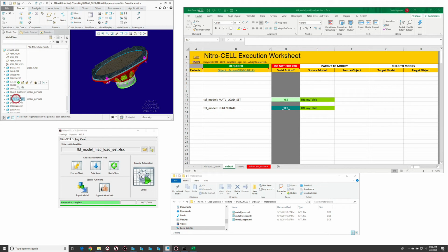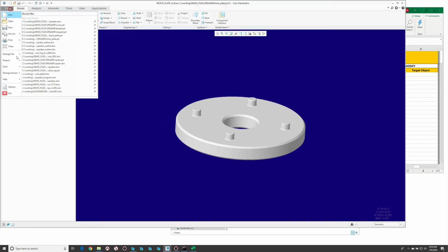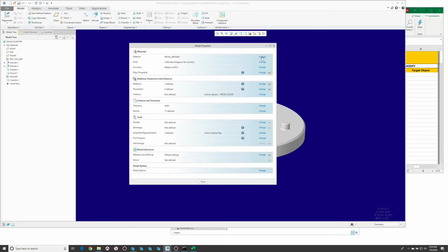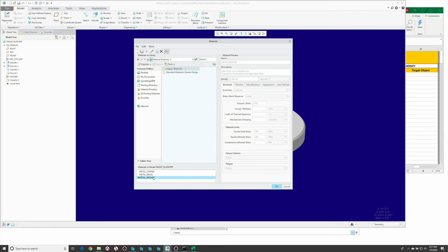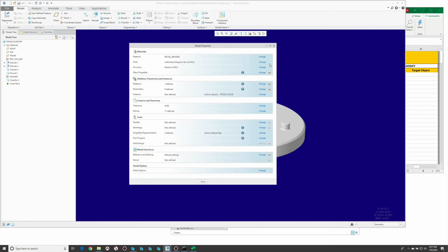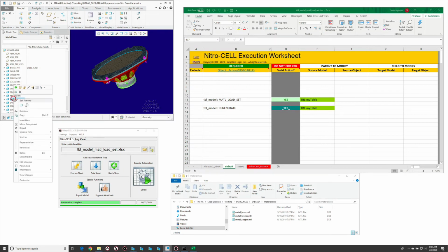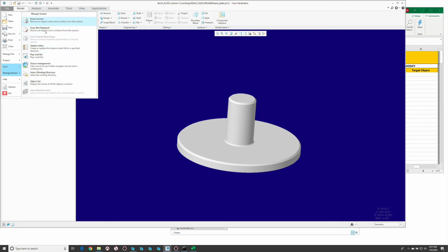Now, the interesting thing about this is that if we go to this front plate that we were looking at before, the load and set is actually a combination function. It's loading the material file and associating it to the model and then setting it as the active. So in this particular case, we've loaded 3 different files and the last one that was set is the one that's active. In the other model, we should only have 2. So let's go back and take a look at that model here. We'll open this one up and take a peek.